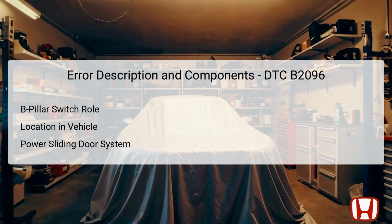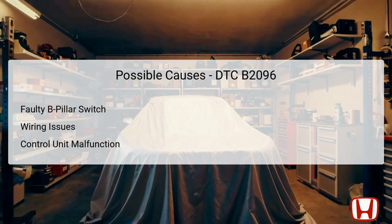The failure of this switch or incorrect signaling can trigger DTC B2096, indicating that the signals for opening and closing the door are being received at the same time. This simultaneous activation can cause conflicts within the system, potentially resulting in operational failure. It is essential to ensure that the electrical connections to this switch are secure and functioning correctly to maintain the system's integrity. There are several possible causes for DTC B2096 in the Honda Odyssey.